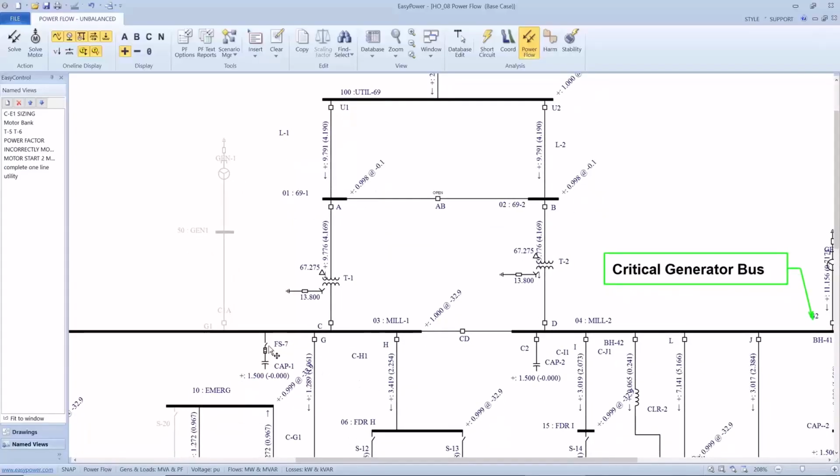And if we exercise that, you can see it change slightly. So this is sustained, but the reactive current doesn't have to go through the transformer. That's the whole benefit of power factor correction on the bus. It slightly brought up the voltage, so that's a good sign, and it reduced the losses that would be experienced because that reactive power now is no longer being drawn from the utility.